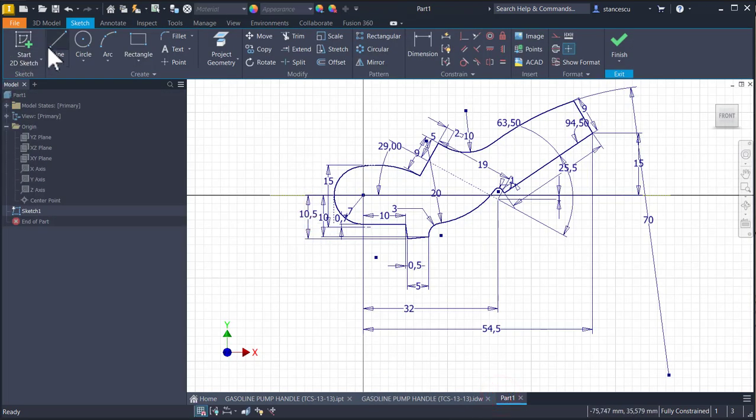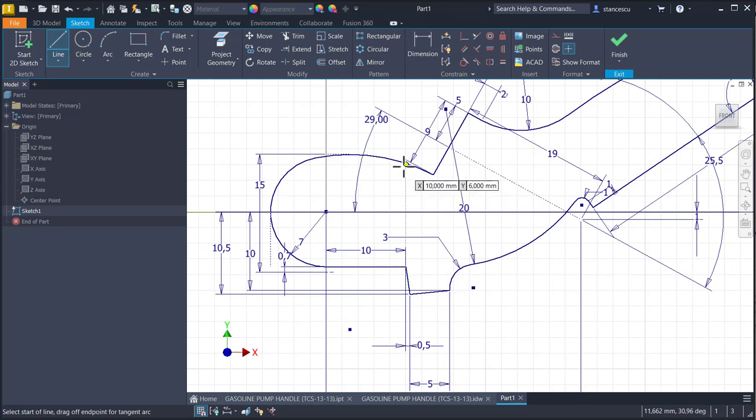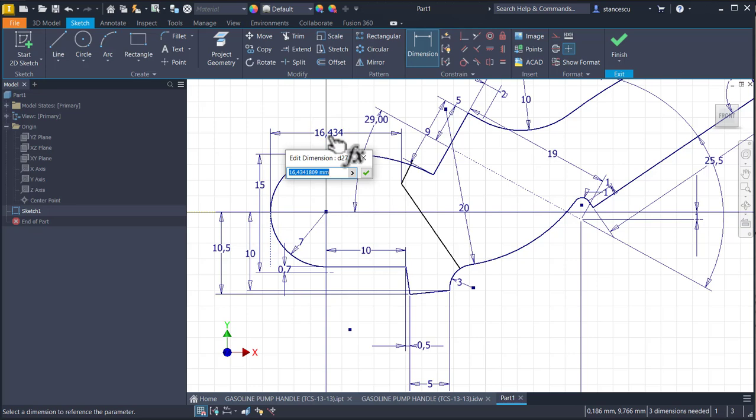Let's do this. Line from a point here and going somewhere here. I extend it to that arc. I make coincident this point with the line. Let me move this 3 value of 3. What happens here? To see better. Then that dimension 16 is from this tangent to the peak point, 16, 11.5 from this point to up.